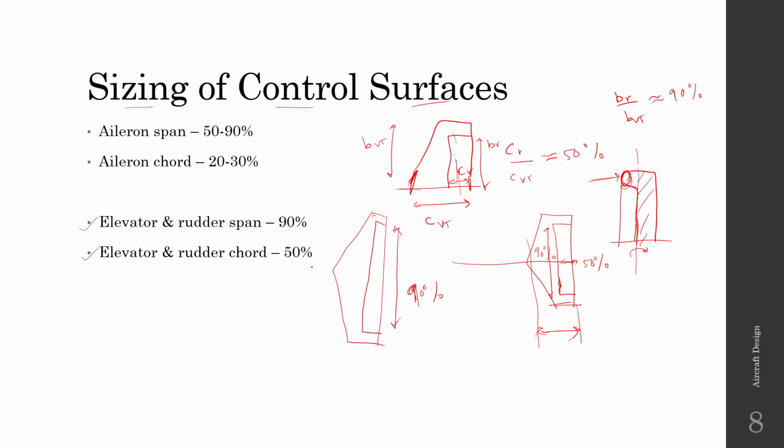And also, you will see that the aileron is used to roll the aircraft, right? So the further away the aileron is from the roll axis, the more effective it is going to be. Even if the aileron deflects over here, it is not going to produce much torque because it is close to the roll axis. The aileron over here, if it deflects, is going to cause a lot of torque. So this area near the center line may be used for other purposes instead of a big aileron, and that is usually the case.